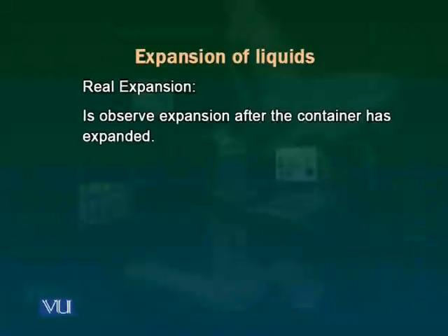And we can always look at it depending upon what material the container is made of. If it is made of material which has a very low rate of expansion, or the coefficient for linear or volumetric expansion is very low, then there is almost no change in the rate of the rise of liquid. However, if it is made of material which has a high expansivity constant, then the level might change at a different rate.